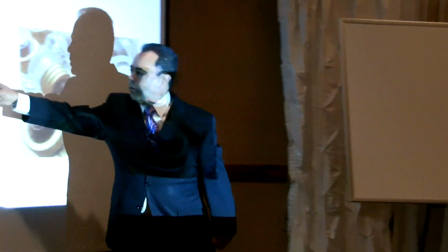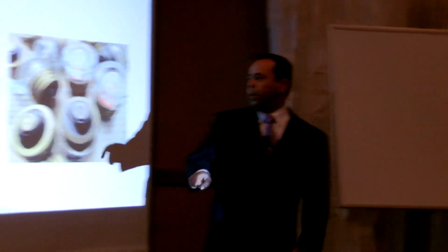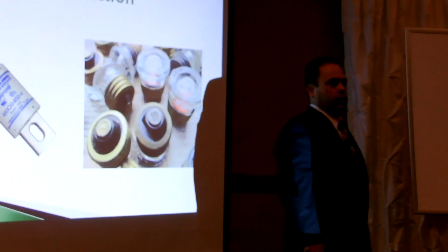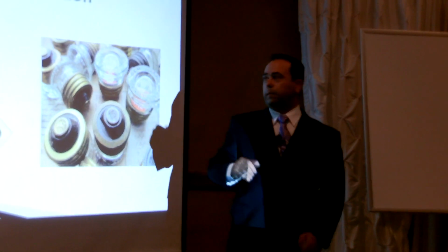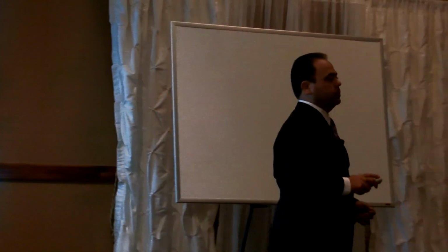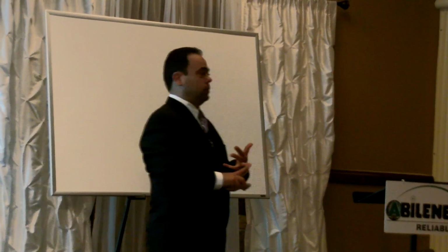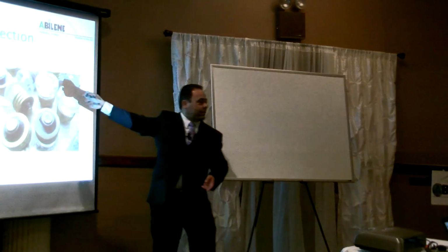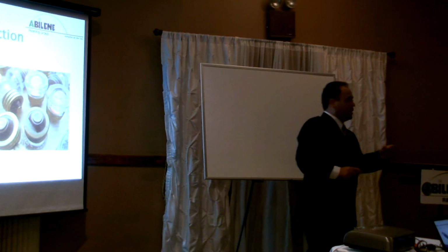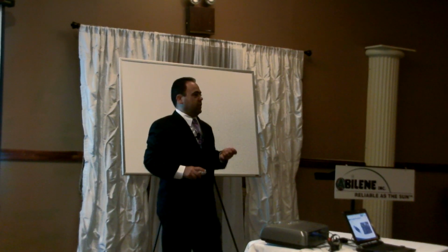These fuses here, there's a link inside there. All it is is a small little wire that's rated at a certain amperage rating, depending upon what this is. This is a 400 amp fuse, all right? And it's filled with sand. Once it blows, everything comes apart inside that fuse, okay? And that's operated by heat. Overcurrent or short current, the heat comes back and burns it off. That's why you see how this gets black. When the fuse breaks, it's black because the heat just melts it off. Remember, we talked about welding, right? It's heat. Electric is heat.